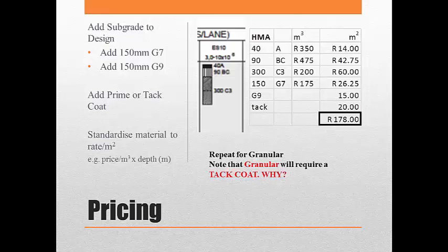If we are evaluating different catalogues and we're putting the same wearing course down, then the most critical layers really become the base course and the subgrade base, because remember, we are assuming the same subgrade for each and every design.